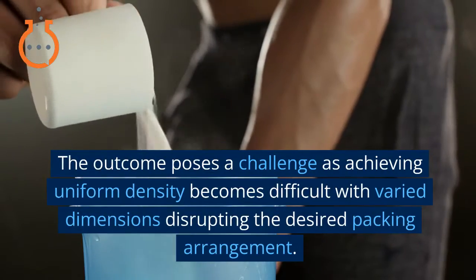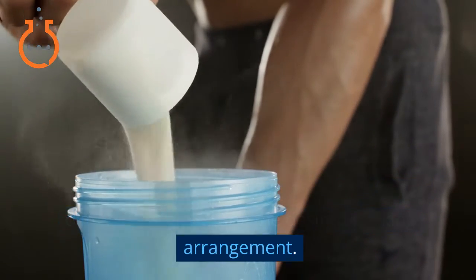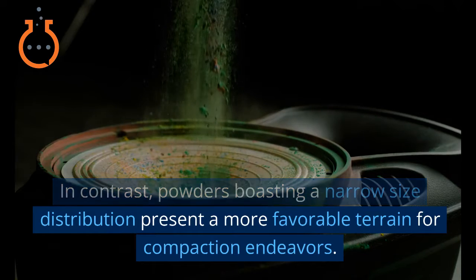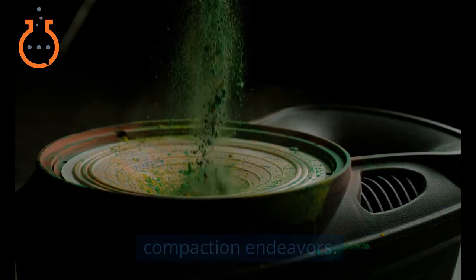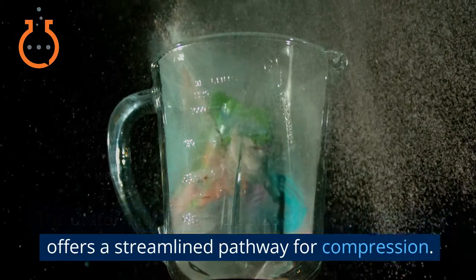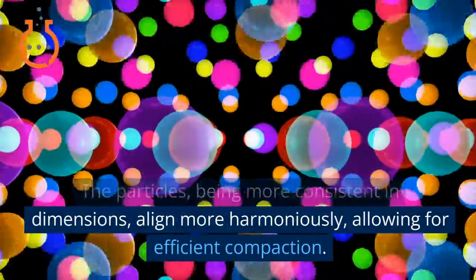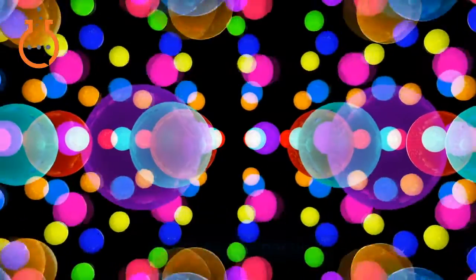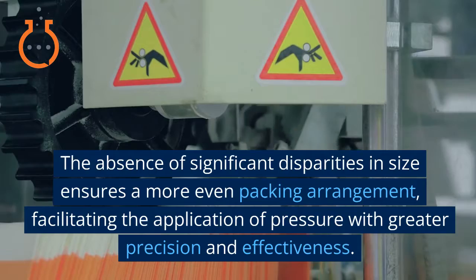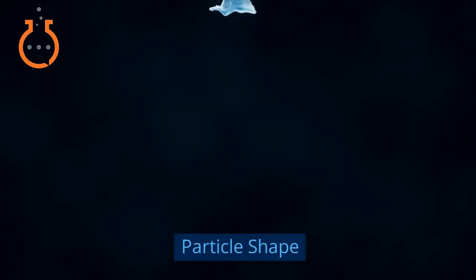The outcome poses a challenge as achieving uniform density becomes difficult with varied dimensions disrupting the desired packing arrangement. In contrast, powders boasting a narrow size distribution present a more favorable terrain for compaction endeavors. The uniformity in particle size within this scenario offers a streamlined pathway for compression. The particles, being more consistent in dimensions, align more harmoniously, allowing for efficient compaction. The absence of significant disparities in size ensures a more even packing arrangement, facilitating the application of pressure with greater precision and effectiveness.